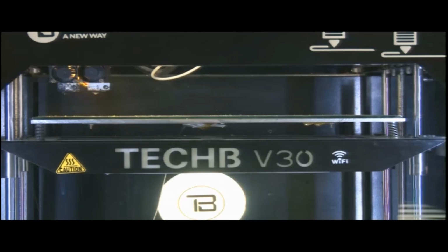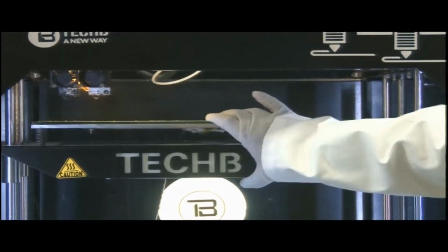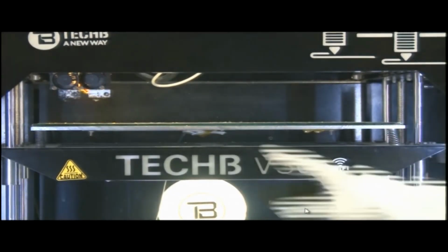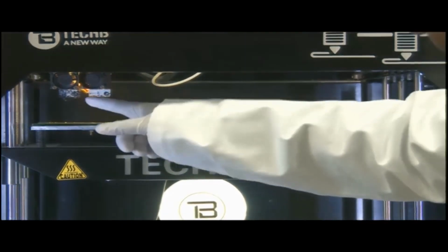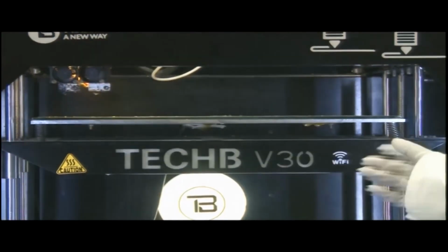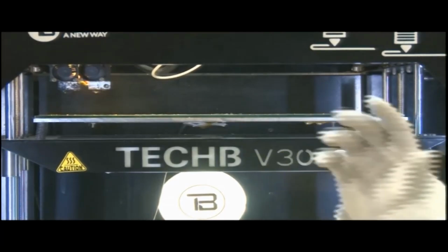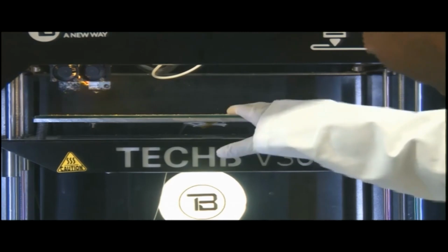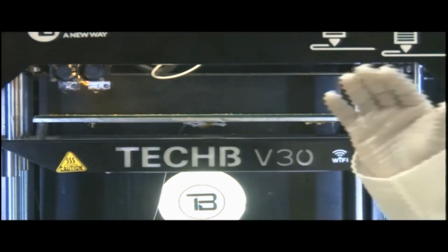When we fabricate a model of big size, the height increases and sometimes it will vibrate due to the height, and the gap will vary. That is why the spring loaded mechanism helps to adjust the movement of the nozzle. You can see the spring mechanism here, which helps adjust the movement. In this way we level the bed. Also, whenever we go for calibration, we use these screws to loosen and tighten, to make sure the bed is flat and secure with its adjacent surface.